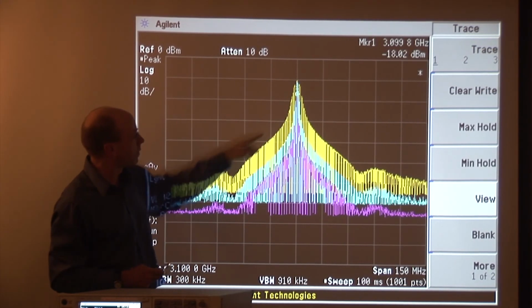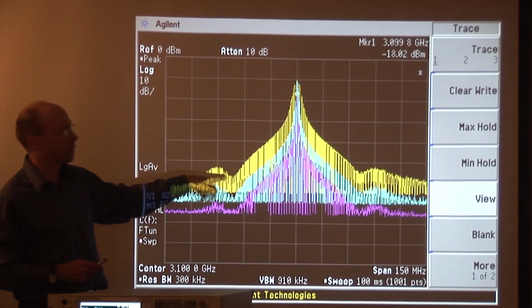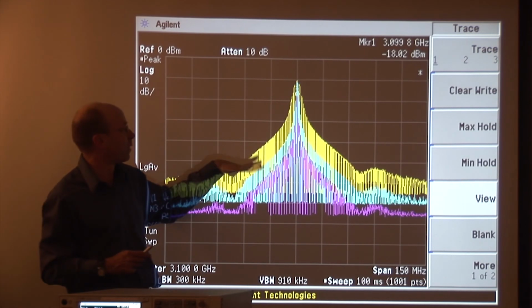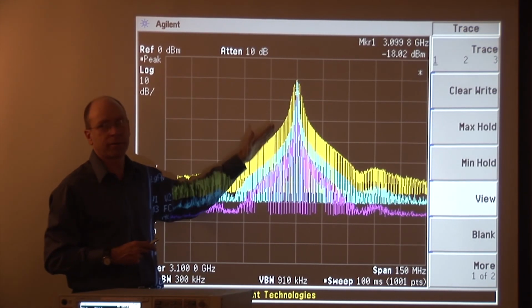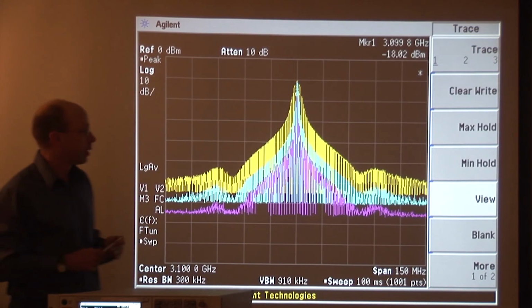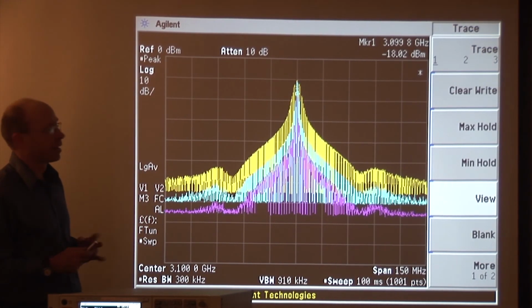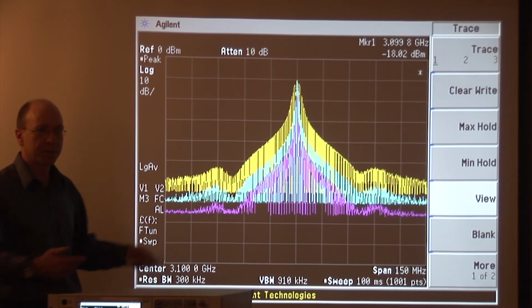If we measure in too wide a bandwidth, we can eventually make the radar fail the mask. But if we measure in a more narrow bandwidth, we can at least get a set of consistent spectrum results we can fit under the mask. This may or may not have been exactly what people had in mind when they designed the mask, but at least operationally speaking, this is a way to deal with it.